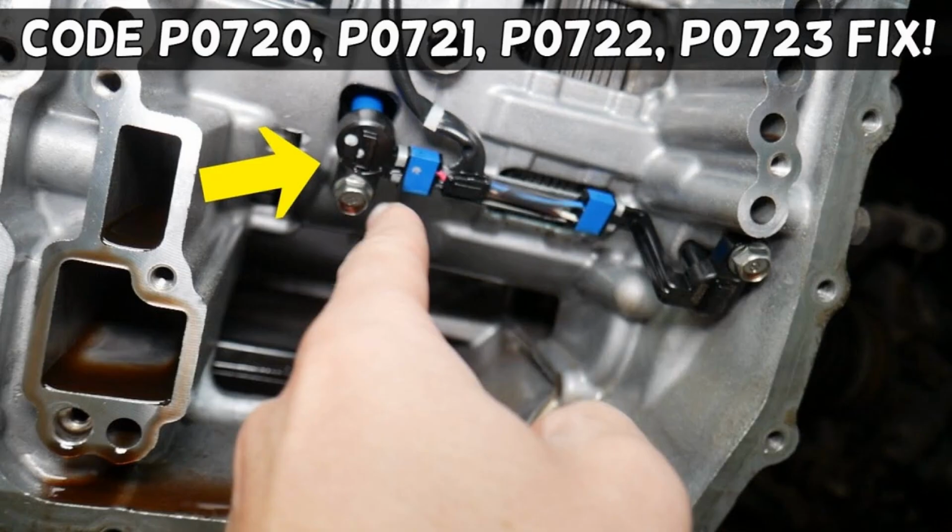In some cars, the OSS sensor is in line with the transmission fluid temperature, TFT, sensor. If the TFT sensor or the associated wiring is faulty, the OSS sensor may also malfunction. Therefore, if there are other errors associated with the TFT sensor with the code P0723, look for a possible problem with any of these sensors or the wiring between them.